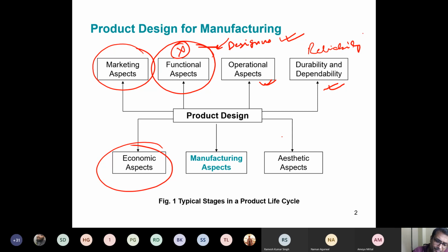economic aspects, manufacturing aspects, and this is where we have to start making it and have to identify what kind of fits we get. Read those drawings and then identify, oh, this is this fit. Okay, and then aesthetics. So I can make these tolerances or these surface roughnesses very, very good for aesthetics, but that's stupidity. As a designer, you should always see and specify surface roughness tolerances only if there is a functional requirement. Making super smooth costs money.